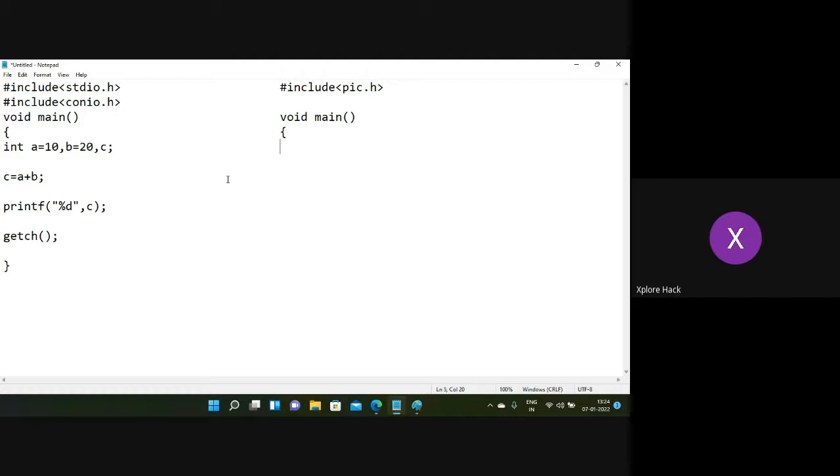If the switch gets turned on, then the LED should get switched on. This is what we are going to configure, but we forget about the other 6 pins. That can cause an exception or some error, because you didn't configure or tell the other 6 pins to act in any state. That's why it can create some interrupt and disturb your functions. So it is better to use these pins within the port.